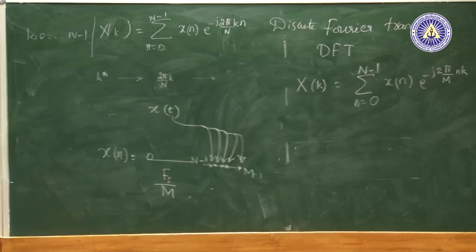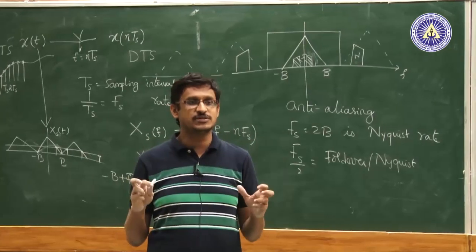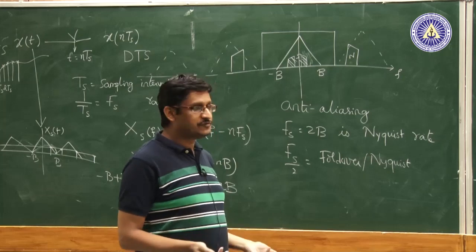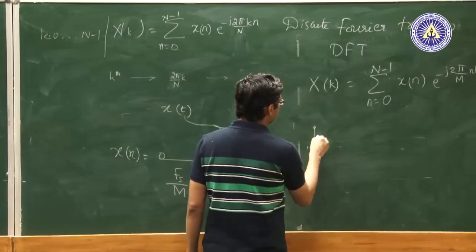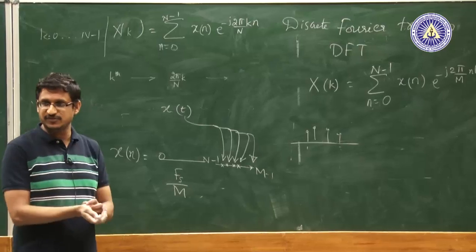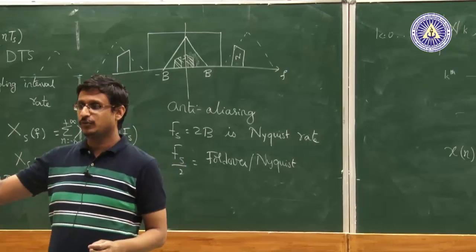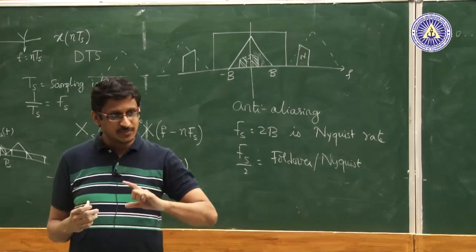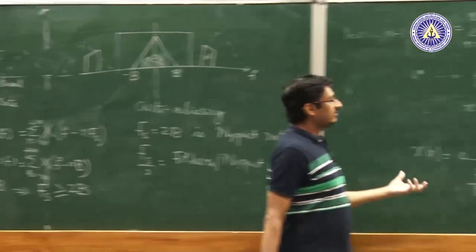Without those correct samples, even if I have increased m and seem to have increased the frequency resolution, or reduced the frequency resolution, whatever way you think of it, I have not gained new information, right. So what in fact would happen is that the energy will still spill over into multiple bins, as we would call them. These are called frequency bins, but then you don't really get only 1.25 and minus 1.25, I mean the corresponding values of k, you won't get only those two things. So just by zero padding, most of the time you won't have actually obtained